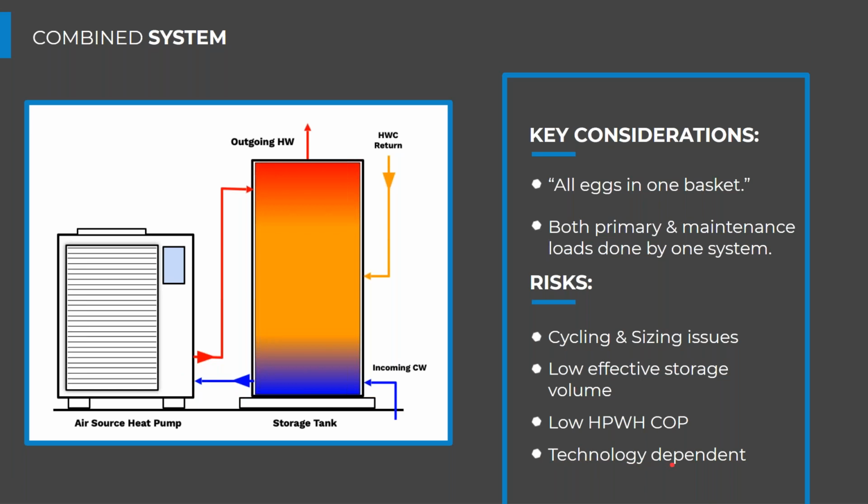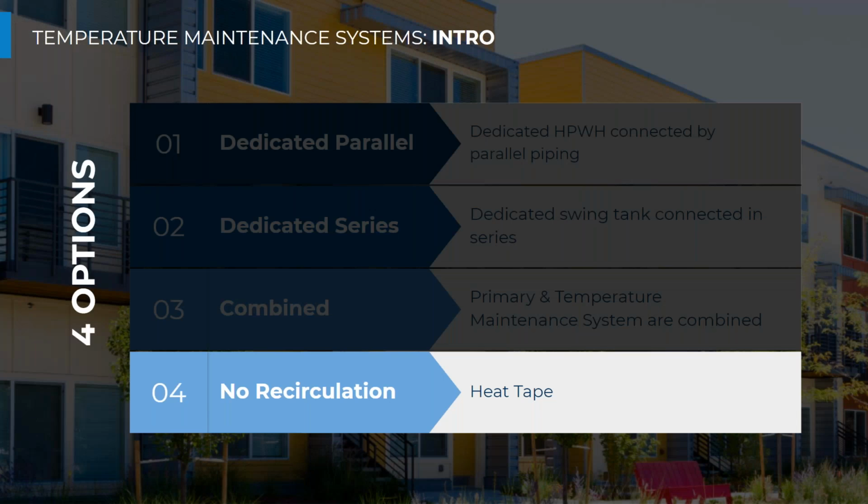And so it's technology dependent. You want to work with your manufacturer to determine the highest inlet water temperature you can operate this heat pump at. And that's going to be in relationship to your outlet water temperature and your air temperature that heat pump's operating in. So once again, this is possible. There's some risks, and that's why we primarily use dedicated systems, either utilizing that series tank.